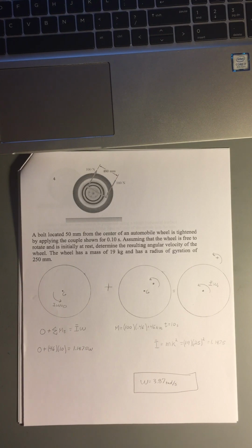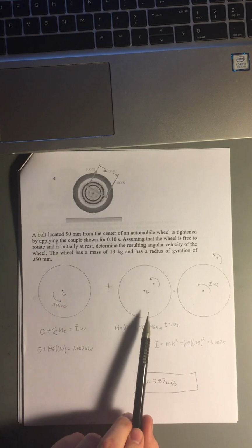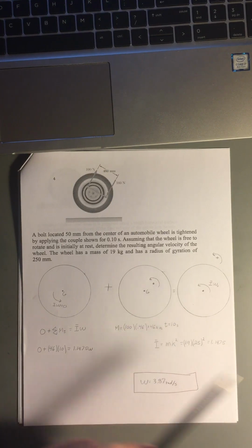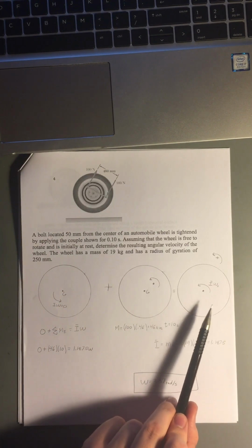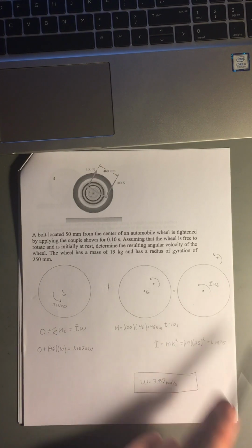And so the first thing I did here was just draw a momentum and impulse diagram to help me visualize it, and then I was able to pull the equations we needed from that. And so here we have the momentum before, and we know that it is 0 because the tire is at rest. It's not spinning when you start using the wrench. And then we add to that our system's impulse, which is just this external force here of the moment created by the wrench. And that has to equal our system's momenta after, which is I omega. And this is the omega that we're trying to find here.